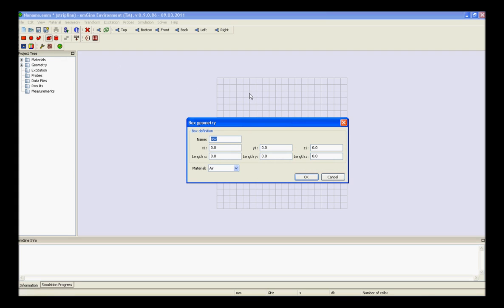The next step is to model the ground plane above and below the substrate. Therefore, you should again do the same process. For this purpose, again go to Geometry, select Box and in the dialog box give the transversal coordinates for both the ground planes. The material setting of the brick must be changed to the desired ground plane. Because no material has yet been defined for the ground plane, you should select PEC as the material for the ground plane from the material drop-down list.